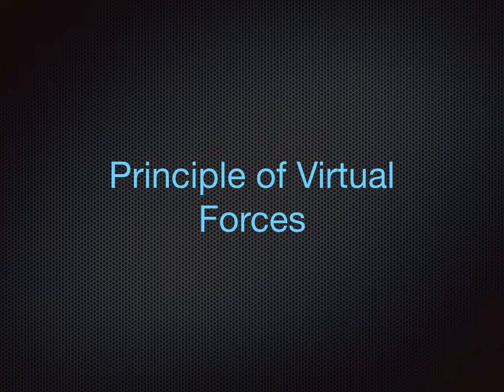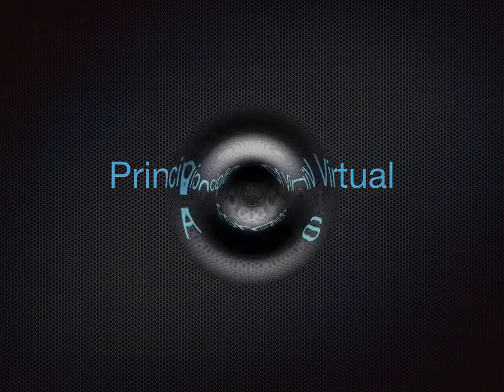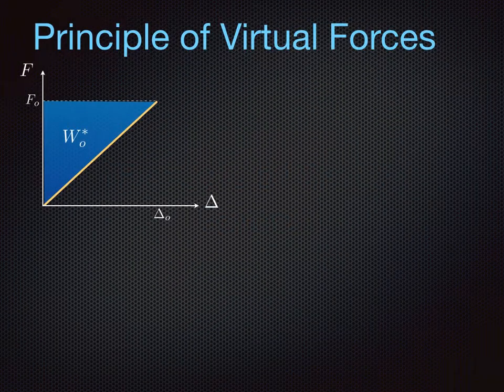Okay, now let's continue our discussion on the principle of virtual work and extend it to the principle of virtual forces. The principle of virtual forces, or PVF for short, works almost in identical fashion to the principle of virtual displacements that we've just seen in the previous presentation, except now it works in the other space. So let's consider, for example, again, a linear elastic system that deforms up to displacement delta sub 0 when we apply a force of magnitude F0.